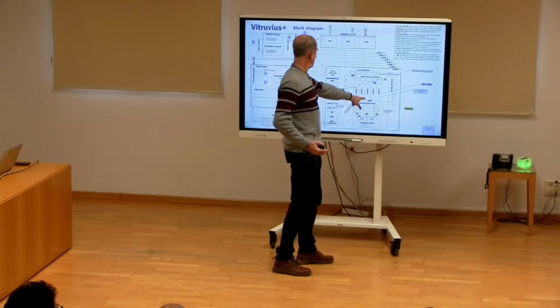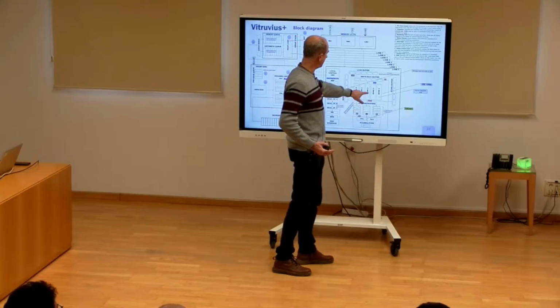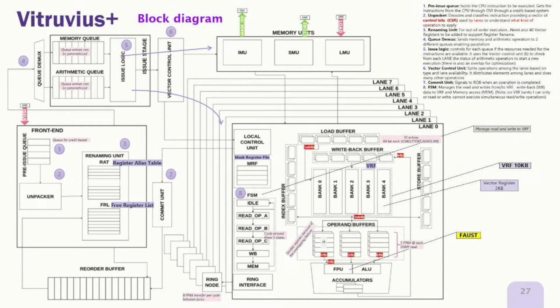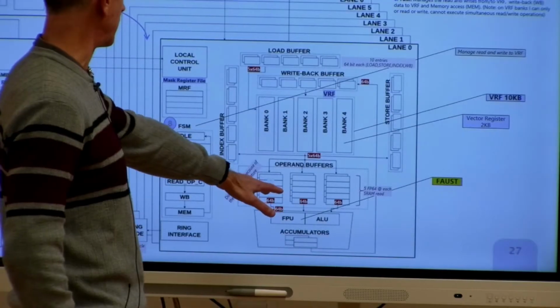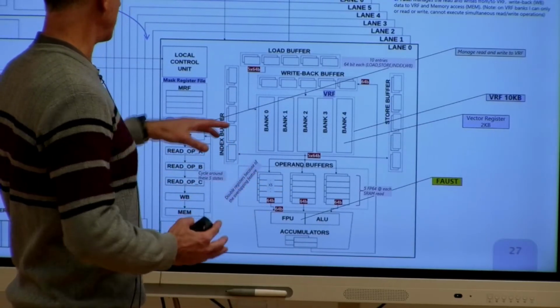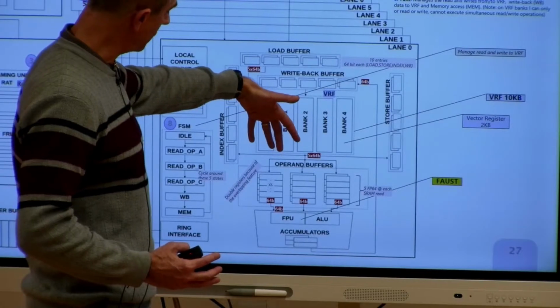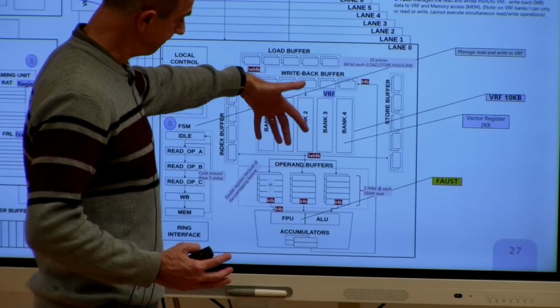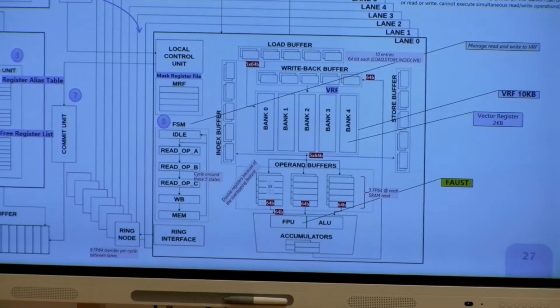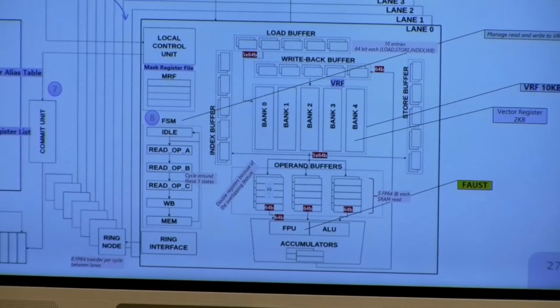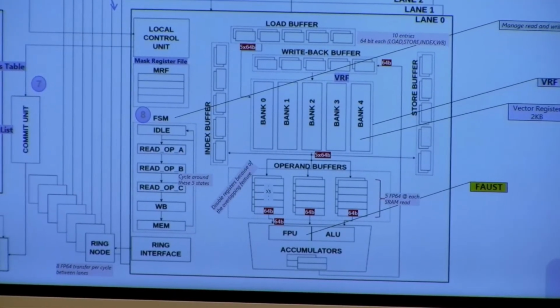You see here, this RAM is 5 banks, 64-bit. Then you read 64-bit from each bank and send this data to this buffer before going to these two units, one the floating point unit and the other the arithmetic logic unit. So this structure is very tied to the way they realized this architecture. Choosing 5 banks is not a good choice because it's not a power of 2. This was my first thought when I saw this structure.